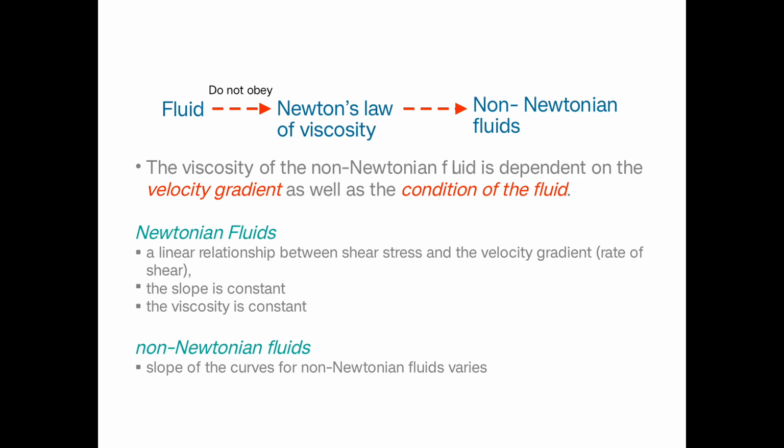When you see non-Newtonian fluids, they always exhibit either a straight line having a y-intercept, which means they need an initial stress to move and then follow a straight line, or they may have nonlinear curves, concave upward or concave downward, which begin from the origin.